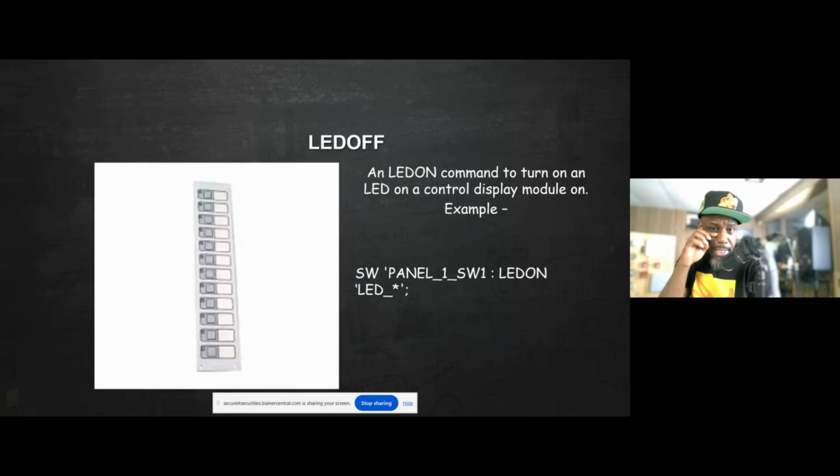And this is what an LED switch looks like. They have the 1224, which is 12 switches and 24 LEDs. This is a 1212, meaning 12 LEDs and 12 switches. The 24 would have additional LEDs, one underneath each of those LEDs. So when you press the button, you can have the top LED do something, and when you depress the button, you can have the bottom LED do something else. So there's a bunch of different things you can do when it comes to the fire alarm system.